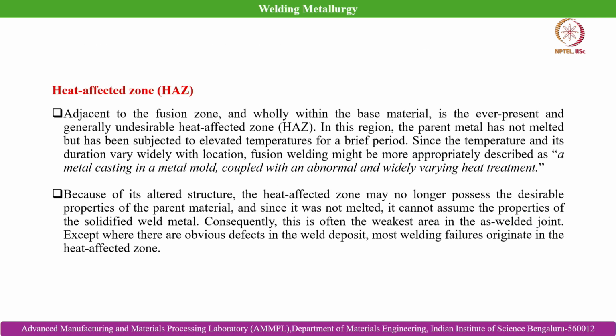Okay. So, now we will move into the heat affected zone. The heat affected zone is basically the weakest region in a typical weld joint joined by the fusion welding route. Again, if I take the simplest example of a single V butt joint, which is easier to explain, assume that this is the weld pool which is formed over here. So, this is the weld pool, and then this is basically the heat affected zone.